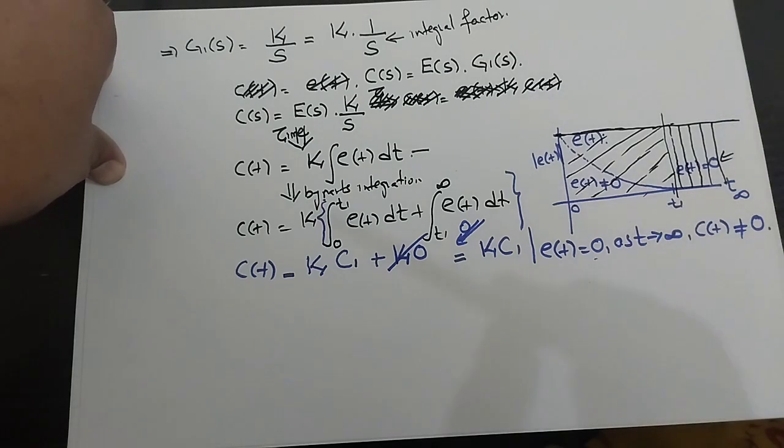Hopefully this lecture has given you insight into the actual scenario that we sketched using this mathematics: whenever we are required to minimize the steady state error of the signal, we need to incorporate integral action. In future lectures, we will use the PI controller, proportional plus integral controller, to minimize the steady state error and improve the steady state performance of the system.